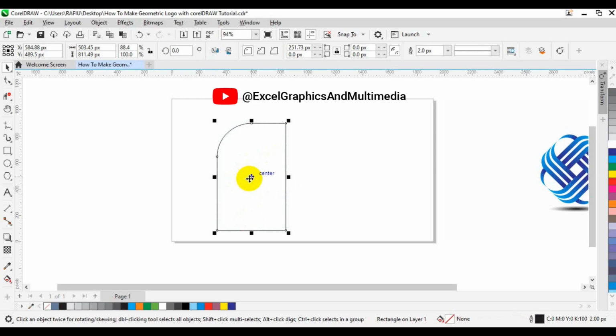The next thing you need to do is to make a duplicate of this. Just press the Ctrl key down on your keyboard and right click and drag it this way. Once you drag, make sure you choose copy here.